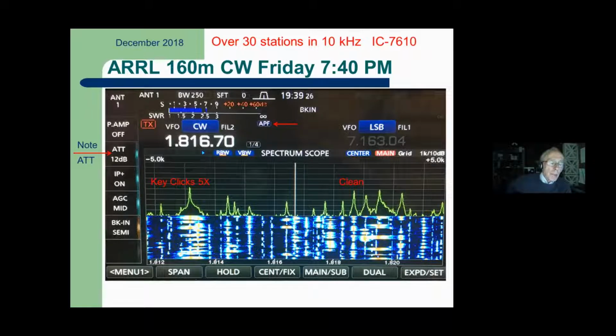But really, we need to pay attention to what band noise is from 6 meters clear down to 160. Just from 10 meters to 160 meters, band noise typically in a quiet location out in the country is 30 dB different, 30 dB more noise at night on 160 than on 10 meters during the daytime. So we've got sensitivity and noise floor to burn.